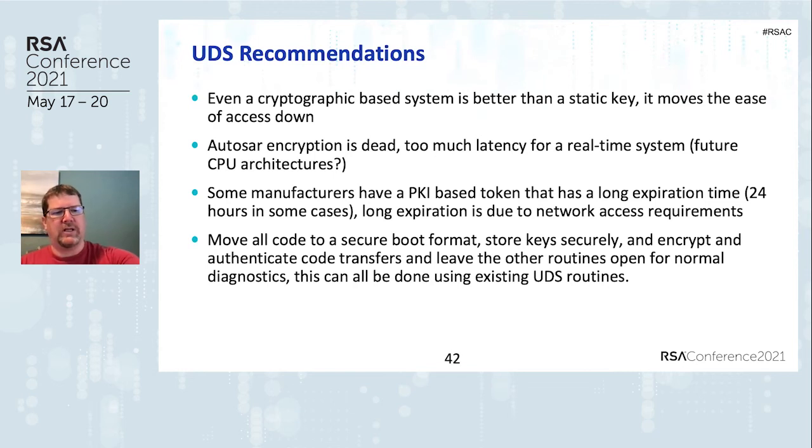AutoSAR was really a proposal to actually implement encryption across CAN bus, but it's pretty much dead. The manufacturers who actually write and create CAN bus systems basically said it introduces too much latency, but maybe with future CPU architectures, we can actually implement something that's some more encrypted CAN bus.